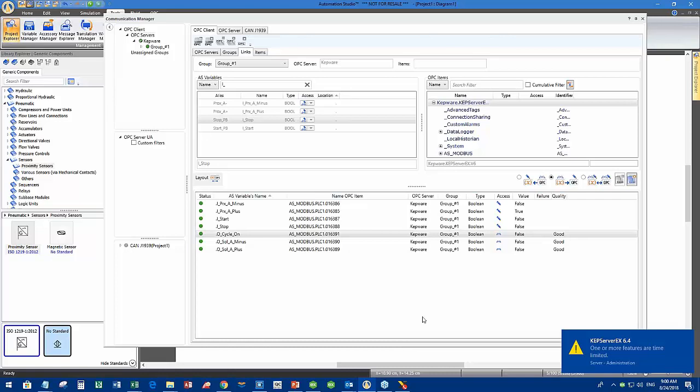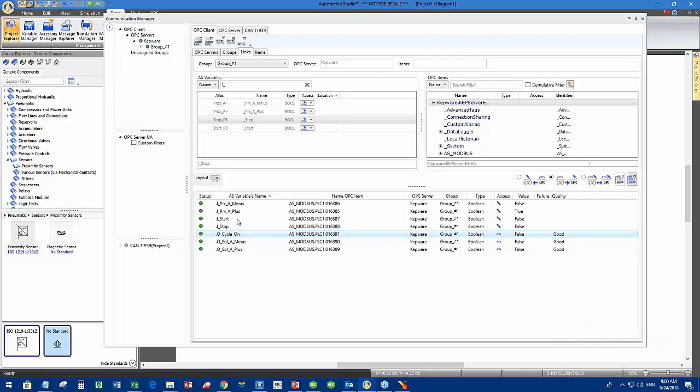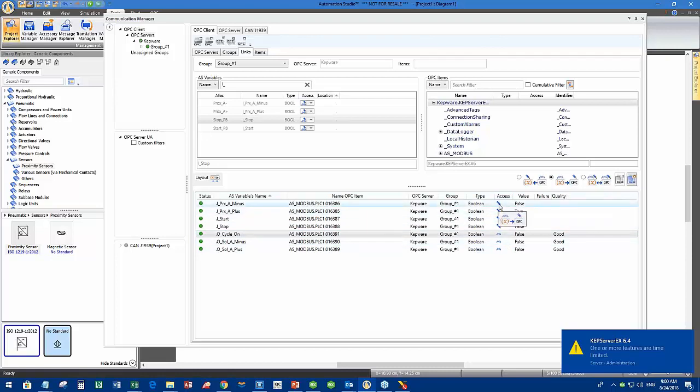Now the only thing I want to specify, if you decide to do it manually, is that for the input, whenever you do the linkage, you select this type of connection, which is the X, which is Automation Studio writing in the PLC, OPC. For the output it is the reverse. It's basically the PLC that will generate a value that has to be written in Automation Studio. So you select this type of linkage. So you see here the access, it's OPC writing into X, and you see here it shows in the access column. This one is this type. This one is the other type.